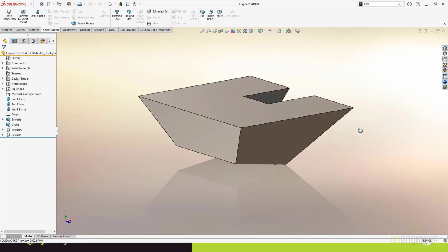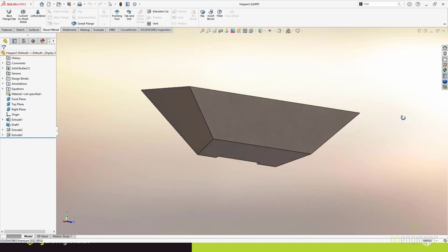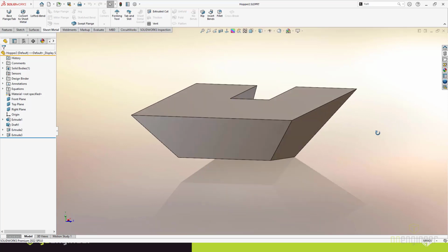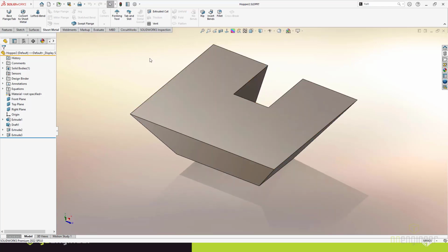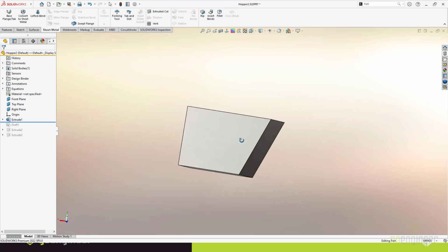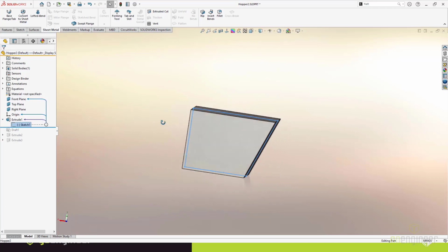But to make this from sheet metal features, it's actually fairly difficult because it's not straight edges. There are a lot of straight edges, but then those edges have to be extended and overlapped. And there's just a bunch of features that you can make it that way. But it really is much easier to make this geometry by just doing what we have here, which is essentially a really simple extrude. I believe it's an extrude from the side shape there if I show you the sketch, right?